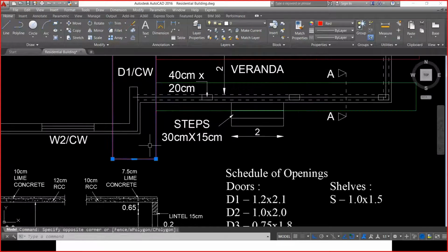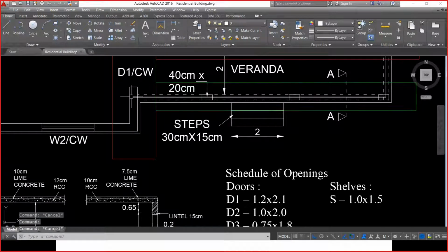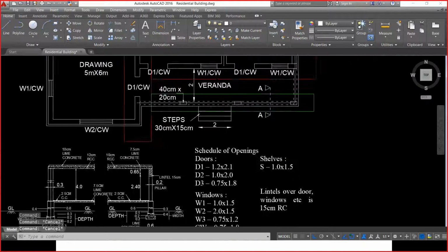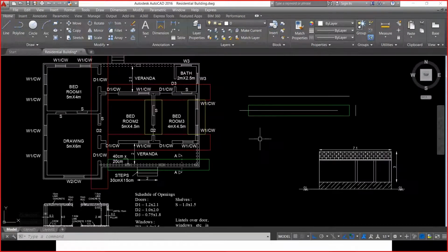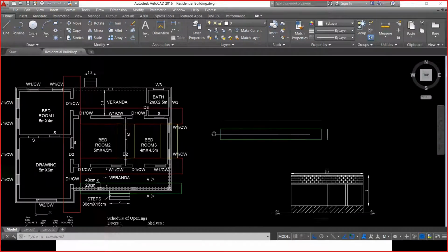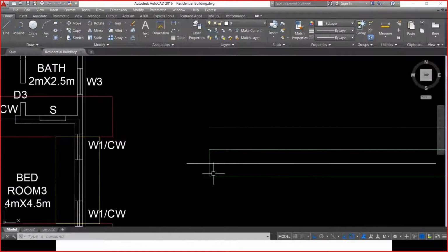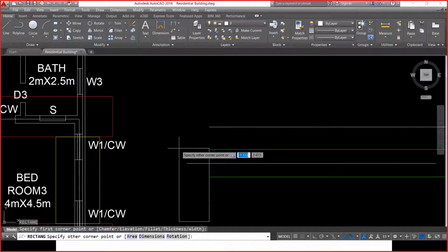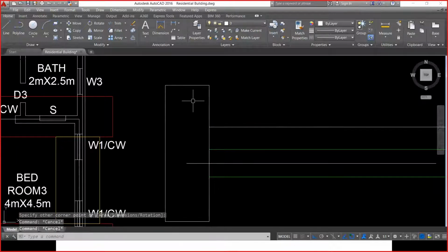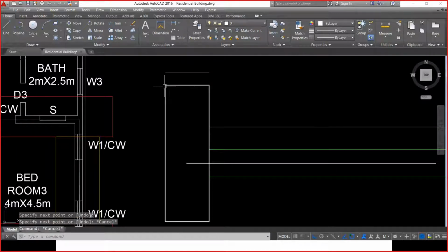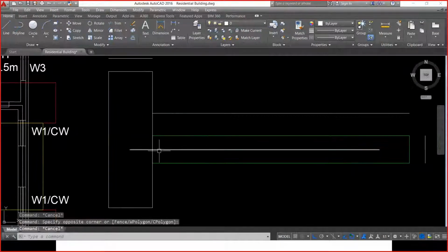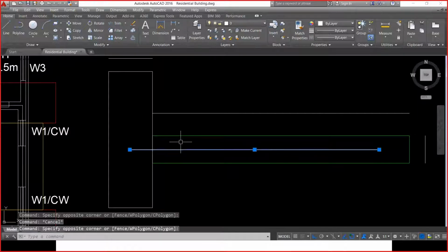Now, this is going to overlap this area or this portion. The additional length beyond this area is going to overlap with the second footing of the main wall. So I know the second footing. The second footing width is 0.5 meter. If the second footing comes something like this, let us say this is the second footing. And this width, whatever you are able to see from this point to this point, this width is 0.5 meter. And this extension is exactly 50% of this width.